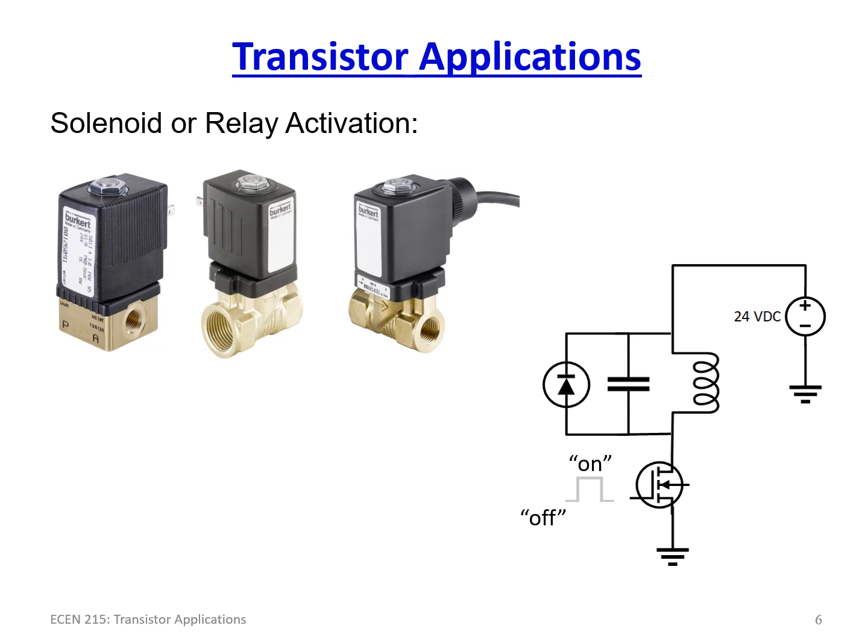Because if I turn on this coil and I now have current flowing through the coil, this inductor is now going to be happy with 24 volts, whatever the resistance of the coil. Let's just pretend for a moment it's 10 ohms right now. So R is equal to 10. So now we have 2.4 amps running through here. When I turn off this transistor, this inductor still wants 2.4 amps running through it.